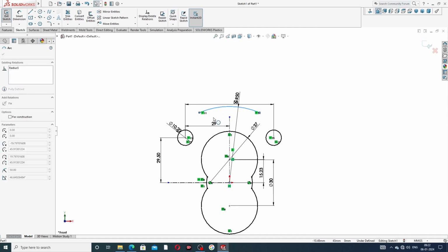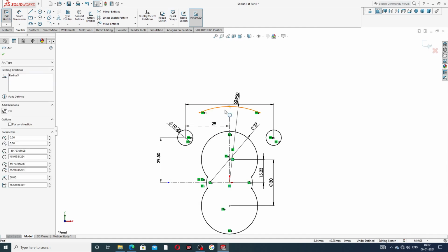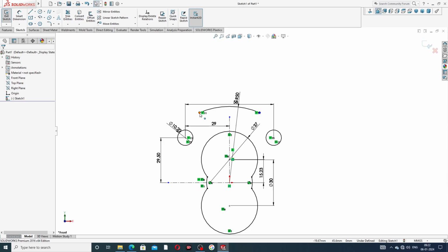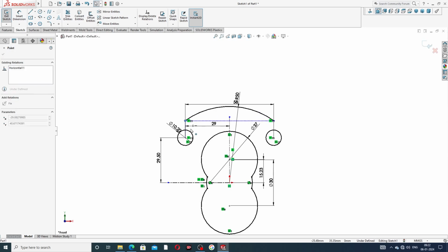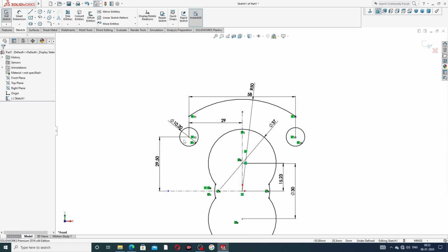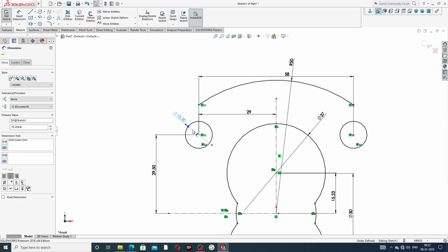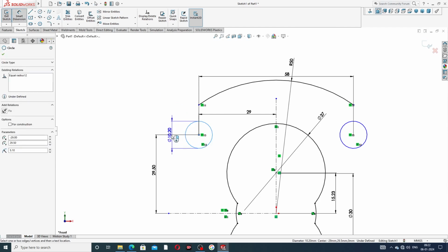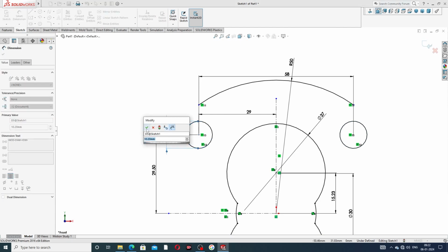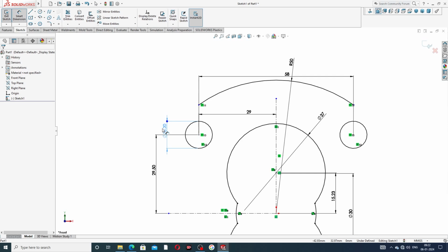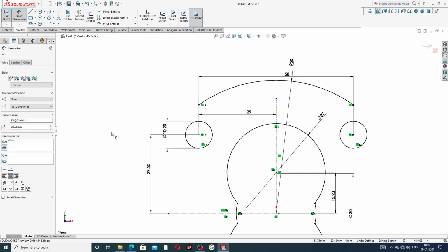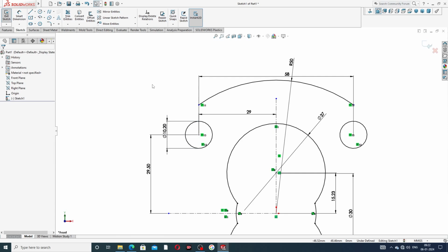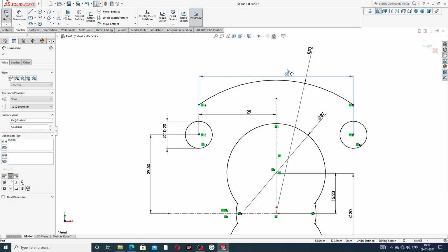And drawing this line, drag here. Okay, this point, drag here. This line, delete here. Define a dimension, the dimension is 10.2. Okay, all is perfect and correct, and this is better.